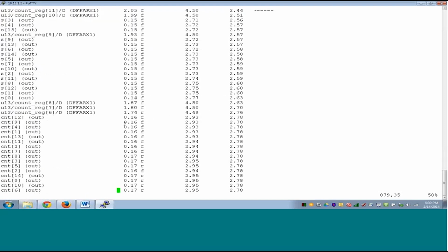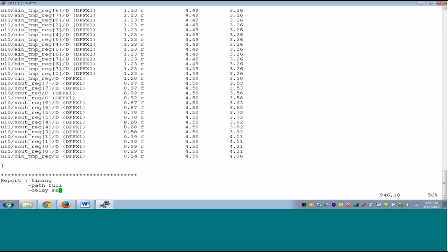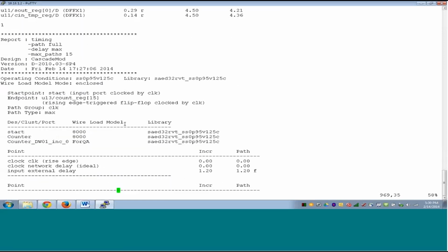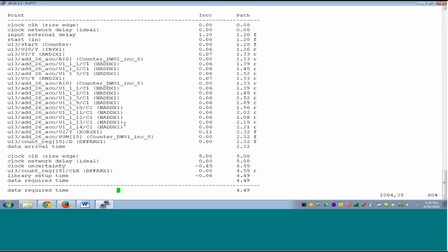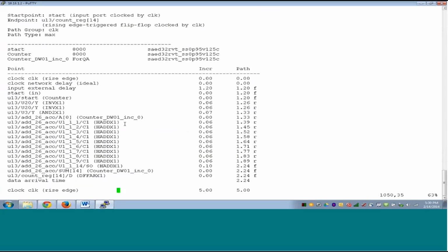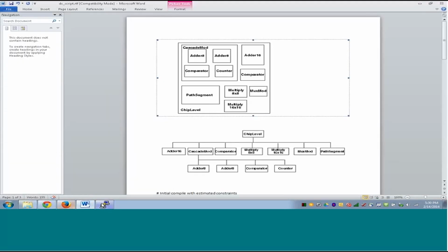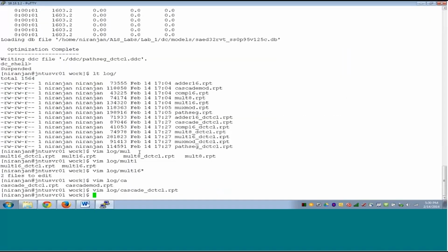And I guess cascade does not even have the GTech logic now, because now the comparator was compiled. It was compiled once. In the first pass, the comparator was being compiled after cascade mod, but in the second pass, let's look at the recompile script again to understand it better.